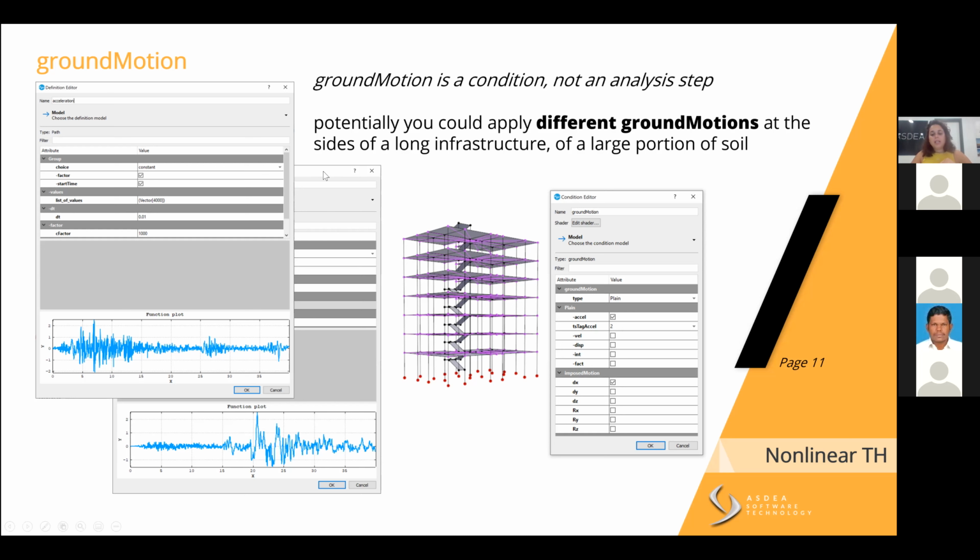And then after being applied, of course, you have to define if it's an acceleration, a velocity input, or a displacement input, and by which factor you want it to be incremented or decremented. Just a note on this: as you saw before, there's a factor in the time series too. So in this case, be careful not to apply a factor to your accelerogram twice, because it's an error that's made very commonly.